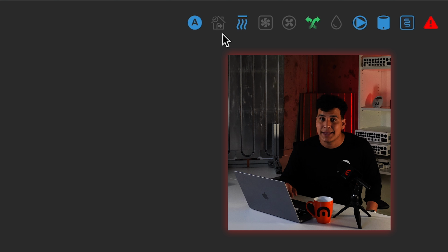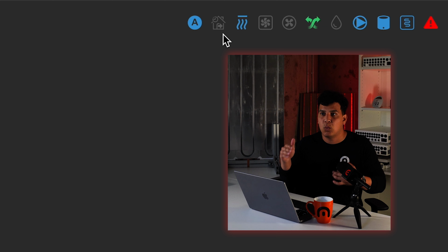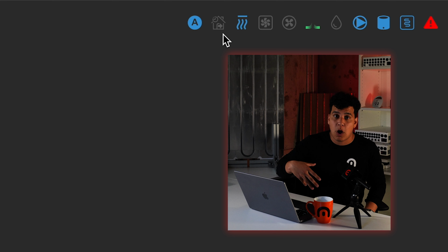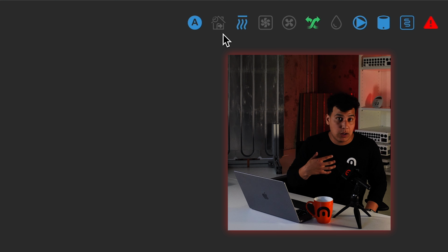This is the setback, and that's a temperature differential that you'll set. Basically, even when your system's off, if you don't want it to get super hot or super cold, you can set a differential so it kicks on once it's getting past that temperature. So here in our office, it's 6 degrees. So if we get 6 degrees higher than our set point or lower than our set point, we'll turn the system on for a little bit to maintain a relatively comfortable temperature. That's not meant for us as occupants, but it's meant to just make sure the environment doesn't get too hot or too cold.